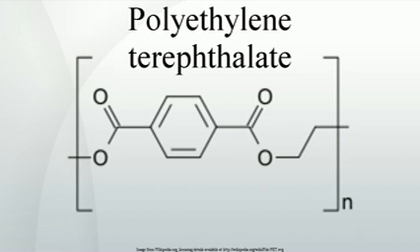Non-oriented PET sheet can be thermoformed to make packaging trays and blisters. If crystallizable PET is used, the trays can be used for frozen dinners, since they withstand both freezing and oven baking temperatures. As opposed to amorphous PET, which is transparent, crystallizable PET or CPET tends to be black in color. When filled with glass particles or fibers, it becomes significantly stiffer and more durable. PET is also used as substrate in thin film and solar cell.